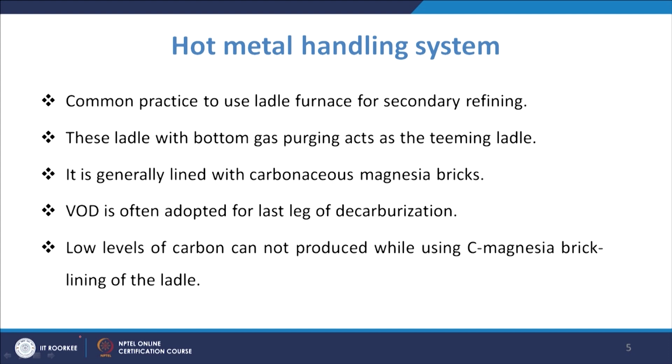When we want an even smaller amount of carbon, for the decarbonization many times we use the VOD process also. While using the magnesia brick lining of the ladle, we can also ensure a low level of carbon.